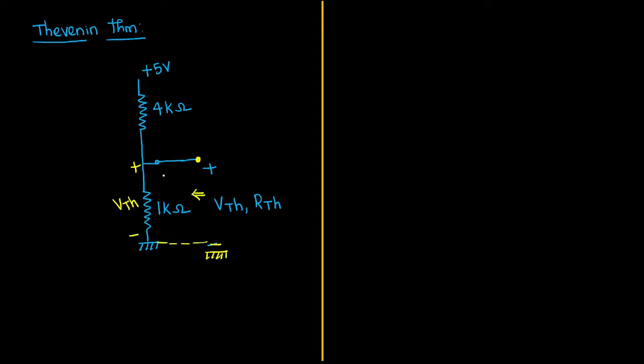We know base current is going to be 0. We have already Thevenized the circuit, so the load terminal is open. Even if they gave the base current, it is 0 now. Why? Because when we are Thevenizing the circuit, the load terminal will be open circuited. When the load is open circuited, the current going through the load becomes 0 ampere. So there is no point worrying about the current flowing through this branch. It will always be 0 when you are Thevenizing the circuit.